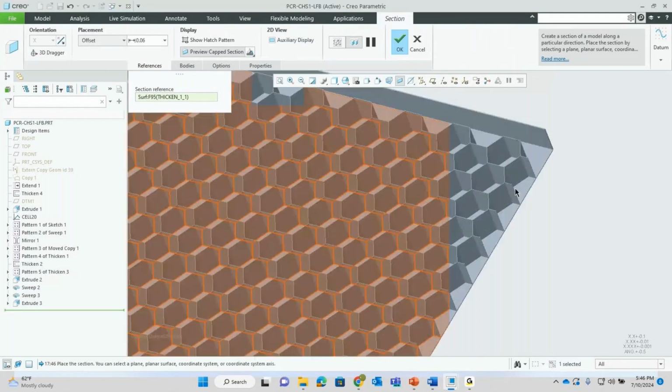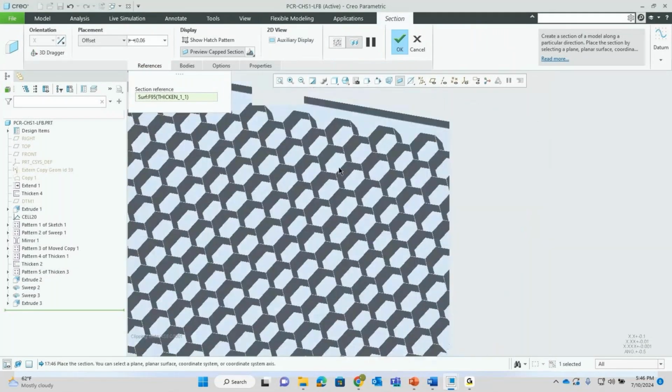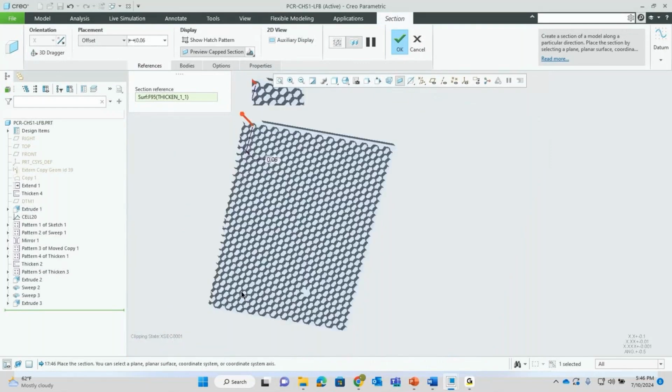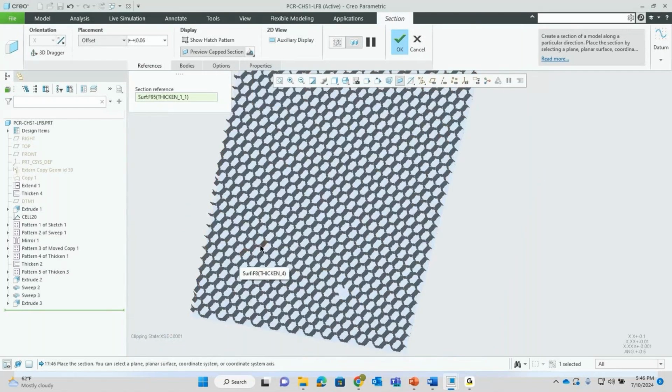Okay, so we have quite a few patterns going on here. We can manage this differently as well. We can create a part simplified rep for this component. Maybe use a different pattern type, like a geometry pattern instead of the normal pattern. Those are sometimes a little bit quicker. So there are lots of tools that you can use, once you find this component, to speed up the process. Maybe you don't even need this component in your assembly. Then you can just exclude it using a rep.